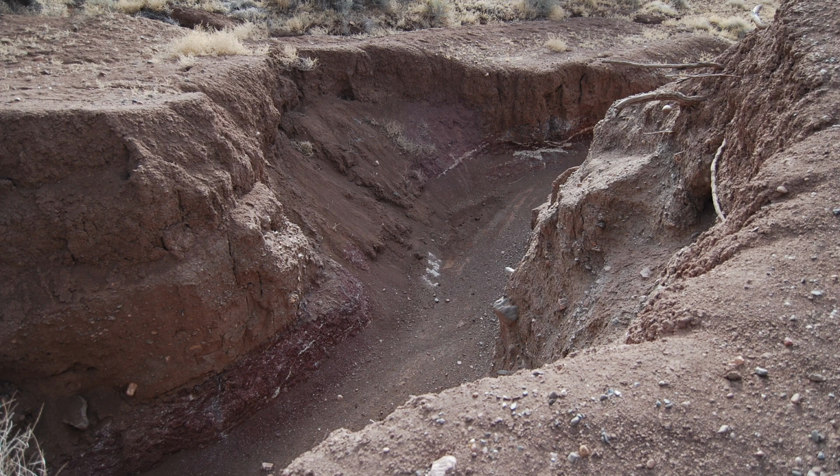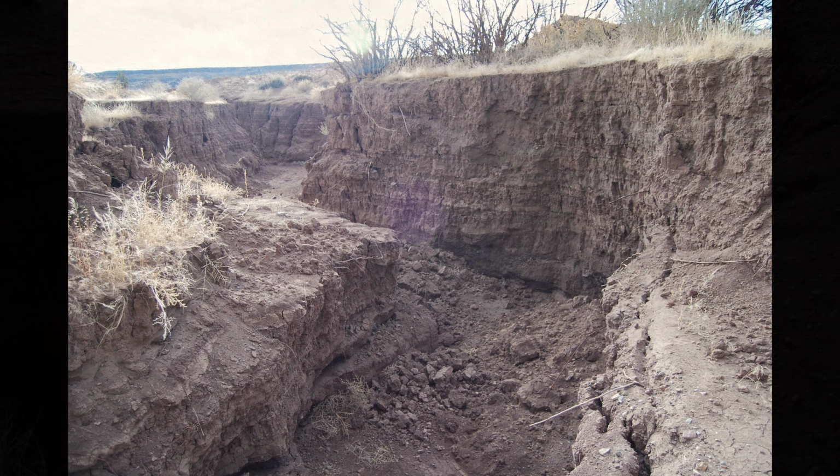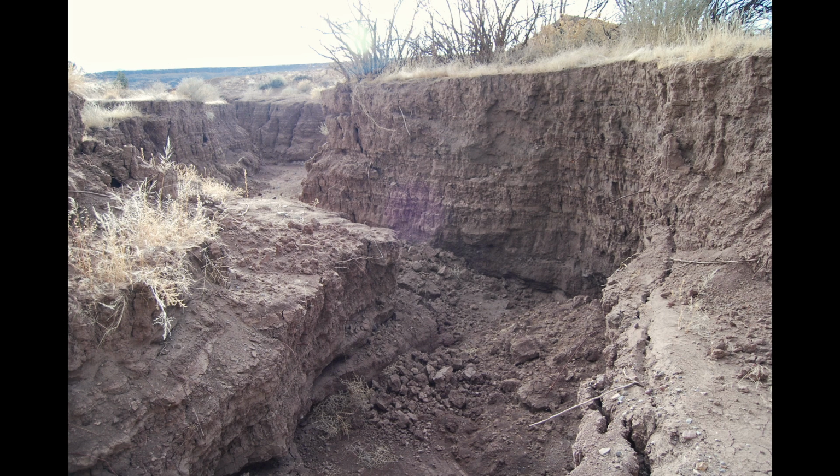The spillway was actively eroding, as one could see roots sticking out of the vertical banks in the side of the channel. It's hard to believe that the simple action of neglecting to build a spillway on a gradual slope that was armored with rock could cause this canyon to form downstream of the pond that was built.